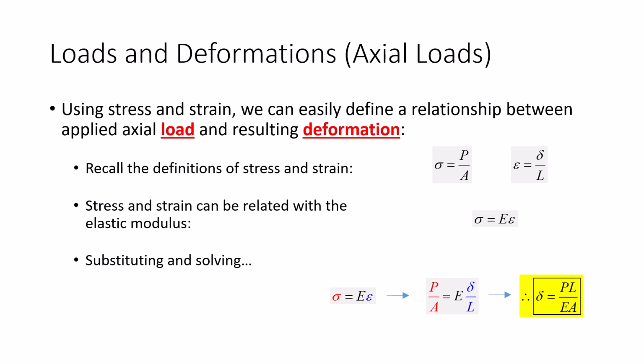Simple, right? Well, for the most part, yeah, it is simple. But there is an added wrinkle that we need to throw into the situation. And that is, this equation assumes that everything is constant. Now, some of those make sense. For example, very rarely would I ever have an engineering system where the Young's modulus appreciably changed from one side of the element to another. If I'm looking at a strut in a car frame, or an element in a truss, I can pretty much assume that element is steel throughout, so I can use the same E value throughout. But it is very possible that some of the cross-sectional properties change along the length.